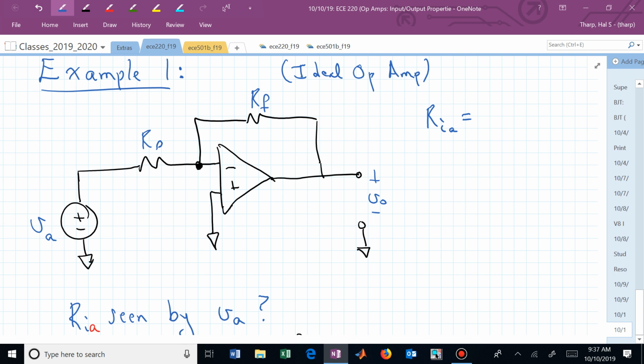I forgot to even follow up. I made that commercial and I got sidetracked. What was I trying to suggest? You're thinking of feedback. Is there feedback in this circuit? And it's negative, so now we have negative feedback, which is a good thing. That now allows us to say that we're going to assume that the inverting and non-inverting pins of this op-amp circuit are at the same potential.